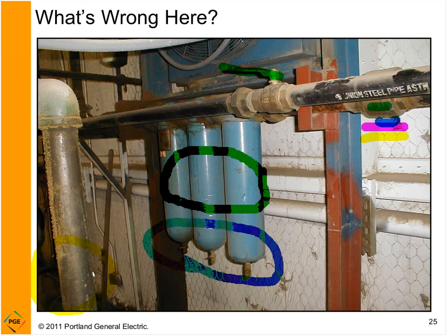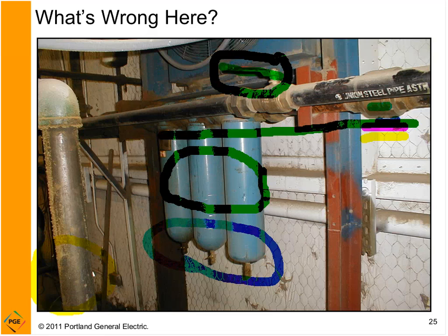Now you look up here, they put more filters in, created a pressure drop. Eventually they had such a huge pressure drop that they had to, as someone's pointed out, crack open this bypass valve. The filters are going through this line back here where someone's drawn.